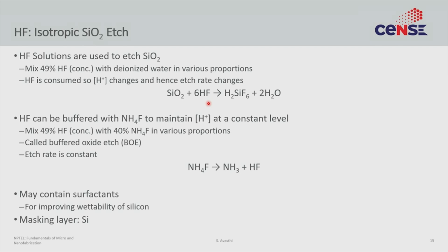However, you do not just put a few ml, what you actually do is take a whole beaker and put the wafer. And what that accomplishes is that you always have a plethora of etching solution, a remarkable excess of the etching solution. And that means that even though you are consuming the etching solution, the absolute concentration of the etchant is not changing too much over the etching period.